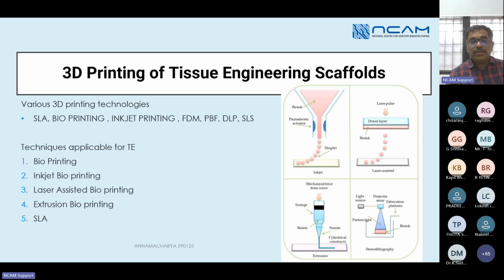We go to the next, stereolithography, what we call SLA, the popular phenomenon which is being used for the bio ink mechanism, where bio ink will be in the tray and then a light source will be hitting on the build plate, and the objects or the scaffolds are being formed. So the major advantage of stereolithography is the media. Media are the resins or biomaterial resins, which help in the development of the scaffolds with that particular tray.